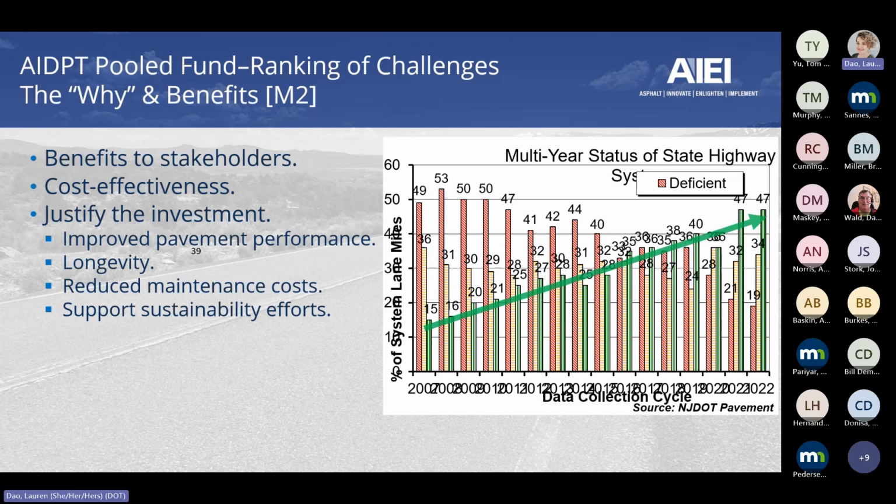This is a graph coming from New Jersey DOT. So back in 2007, they implemented what they call those specialty mixtures. I think we heard earlier this morning about the HPTO, high performance thin overlay, the HRAP, the high RAP mix, and then it goes on, the BRIM, and whatever. It's hard to keep up with the terminology. But those are really specialty mixtures designed specifically for a given application, whether it's a thin overlay, whether it's a medium layer, or like a crack attenuating layer, and so forth.